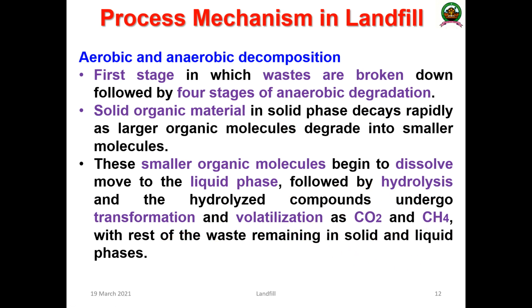I repeat once again. The first stage, this is very, very important. The waste materials are broken down in 4 stages by anaerobic reactions, and the solid organic material in the solid phase decays very rapidly, and the organic molecules degrade into smaller molecules. The smaller molecules start dissolving and move to the liquid phase where hydrolysis takes place, and the hydrolyzed compounds undergo transformation and volatilization, which forms carbon dioxide and methane.